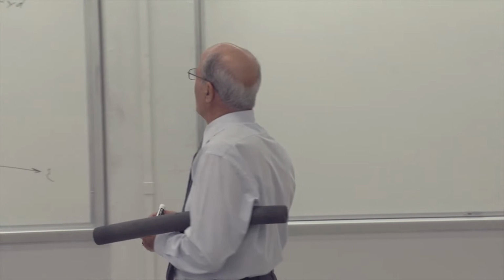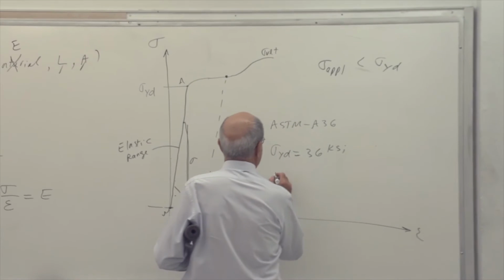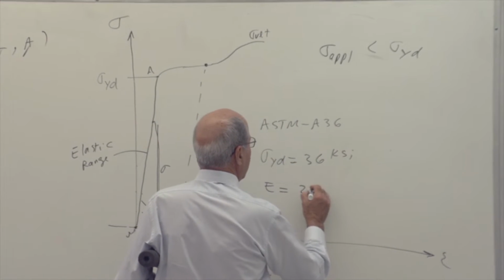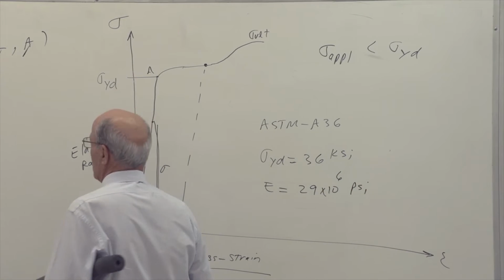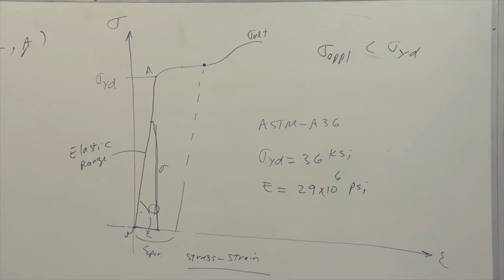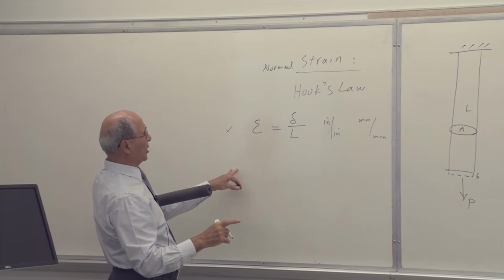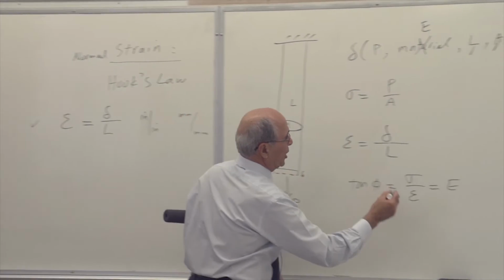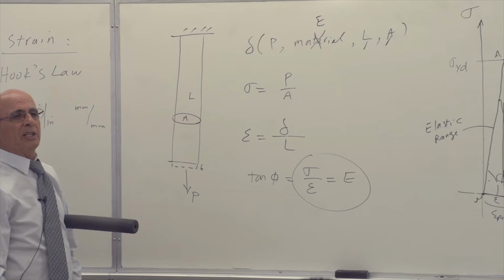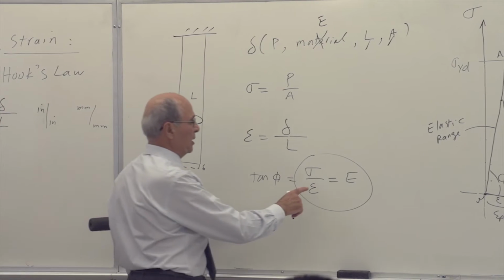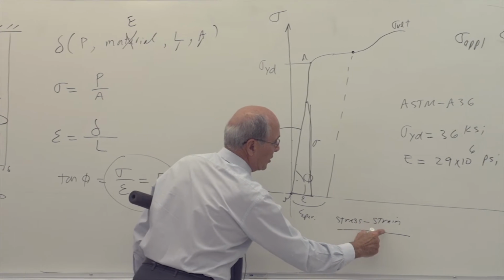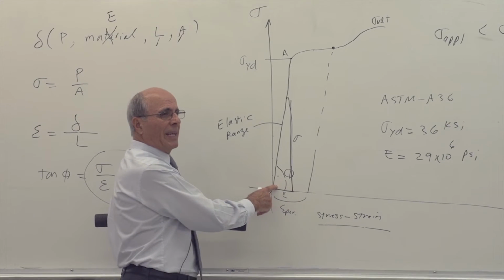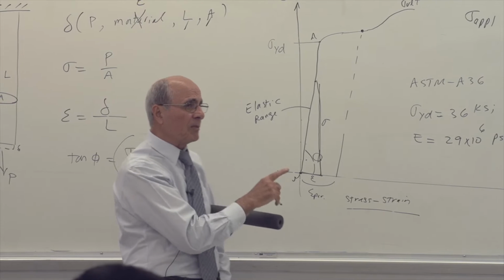And look at the modulus of elasticity. Modulus of elasticity becomes equal to 29 times 10 to the power of 6 psi, because look at the unit here. Let's go back to the unit. Now, this is the new equation. You already have there. Now, notice from this curve, I got a new equation here as well. Everybody understand what happened? The relationship between epsilon, actually this curve is stress and strain and modulus of elasticity. You should remember this. This curve is very important.